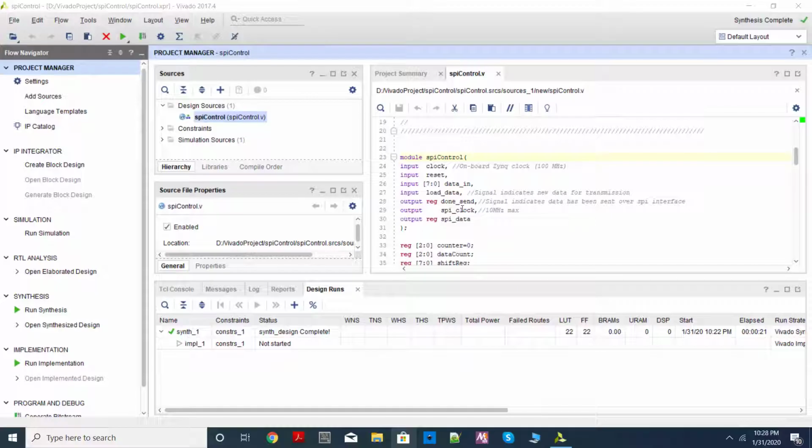Now, this scenario we discussed last semester for digital IC design also. There we had the idea of scan chain insertion, I guess you remember, where we put an additional circuit within the chip and connect some key flip-flops to this chain, and during runtime you will be able to see what is happening with these flip-flops using a serial interface. So here also the concept is similar, but here the advantage is that scan chain insertion is, again, mostly automated.